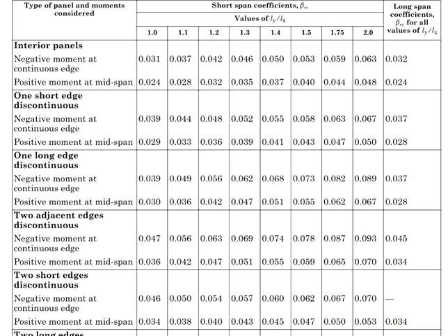Another reason for not designing for different moments is due to practical considerations. You have to consider the supervision process done by the site engineer. In order to make the supervision process easier, the designer tends to simplify the design with as minimum variety as possible in terms of the design outcome. The more variety in the arrangements of the reinforcement, the more time will be spent while supervising the construction of the structural element. Therefore, normally in industrial practice, most of the slabs will have a similar amount of reinforcement, so that they don't easily mess up dealing with different arrangements of reinforcement for different slabs.